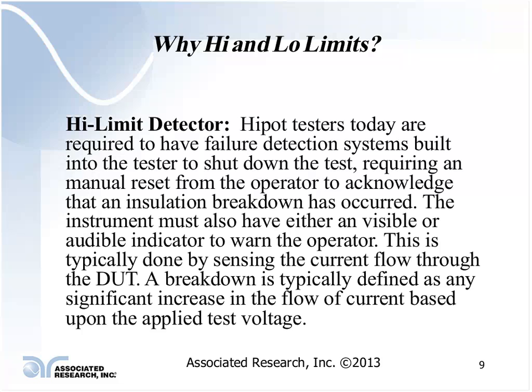It does require you to set the low limit. Okay, if you have the low limit set for 0, it does not help you, because you're going to be drawing more than 0 leakage current during your Hipot test. So, you must set the low limit in order for it to provide you any benefit in knowing that a test was actually being performed on your product.